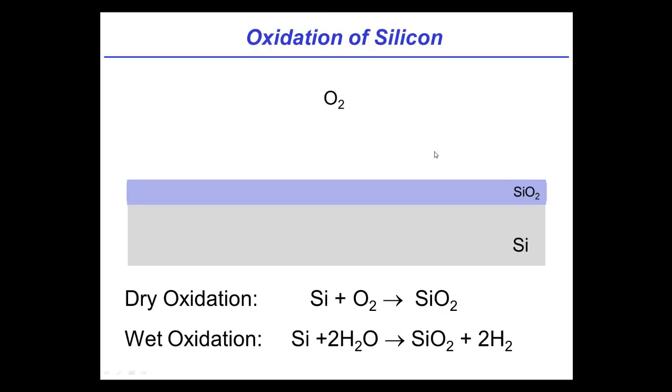And I think that's a great point. So there are other methods of putting SiO2 on the surface of a wafer, which I'll touch on one in a minute, or Vivek will, but the important thing is this makes very high quality SiO2. And it's one of the reasons processing is so successful on silicon is that the quality of these insulators is really very good. So, okay, let's look at another method.